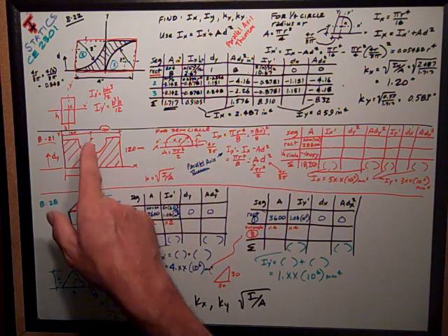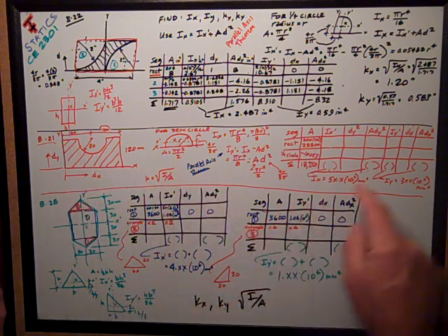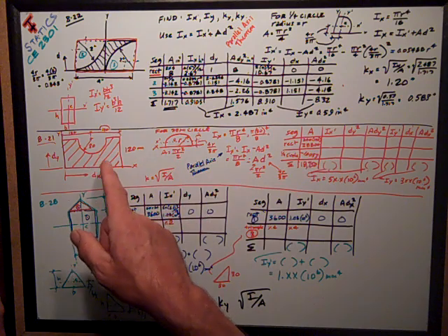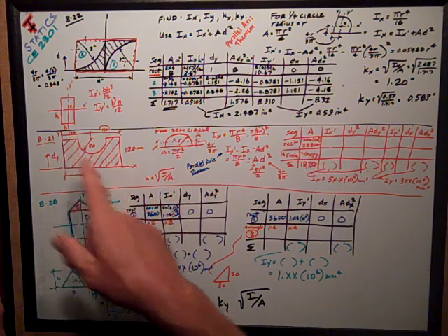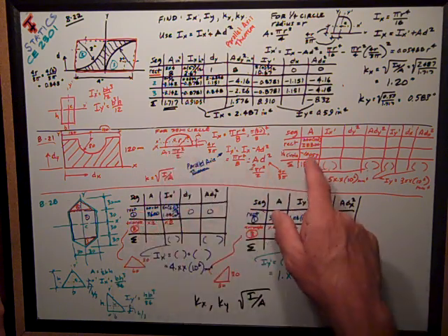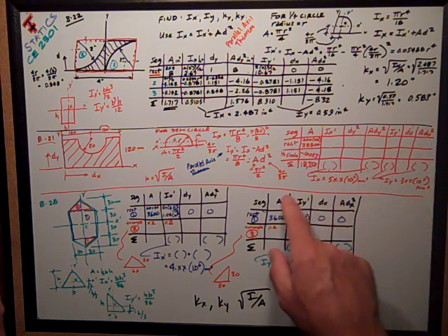And you can get the Iy prime about its own centroidal axis from a chart. Plug that into there. Its dx distance for the rectangle is that 120. Same thing for the semicircle. Remember that it's a negative area. Square those, get that term, sum them all up.